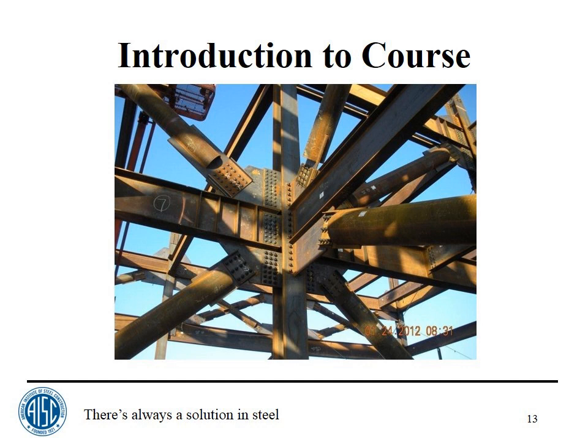I mean, that's got shear tabs to the web. We got 3 columns of bolts. I mean, it's got lots of bolts. But the erection on that was really slick. And going into the column web, we've got on that one, I think, double clips. It's hard to see in the picture, but I'm pretty sure it's double clips. Double clips would, I think, be the second choice. End plates is probably the third choice in terms of economy.